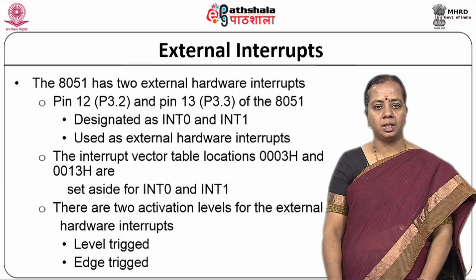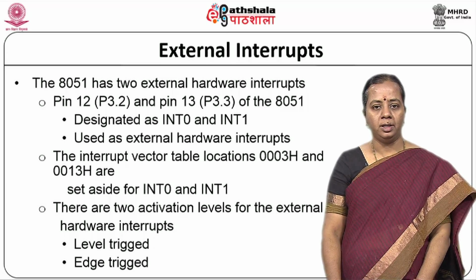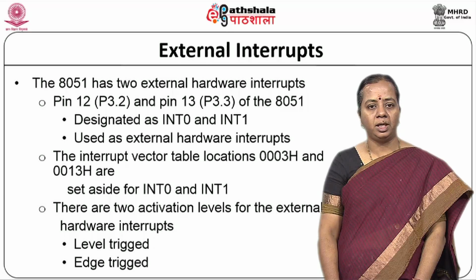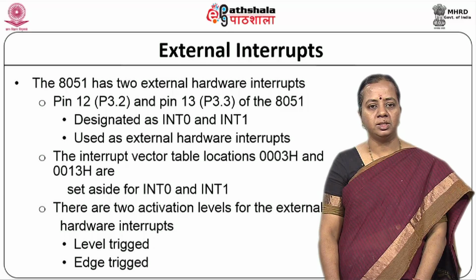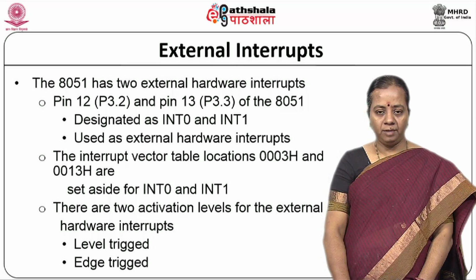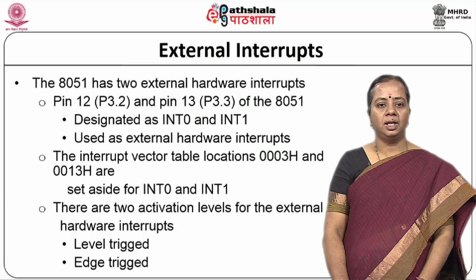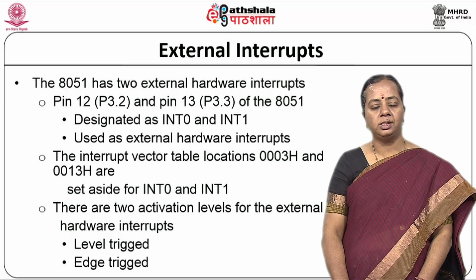One is INT 0, another one is INT 1. These are associated with the pins P 3.2 and P 3.3, which are pin 12 and pin 13. If I provide a signal at these pins, it invokes the external interrupts.